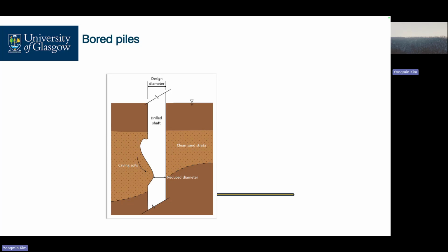So after pouring mass concrete and curing the concrete, we can do some integrity tests and then check the mass or volume we plot. Then we can calculate the concrete volume, then compare them, whether our design concrete volume is placed in this borehole.